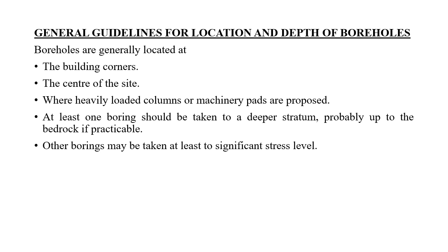Then, as I said, mostly you have to take when you have a plan in your hand. If the plan is already available, then it is always better to do borehole testing. You can dig a borehole beneath all the columns, wherever the columns are coming, as well as wherever heavy machineries or other heavy loads are coming. Okay, then it is always ideal to take the boreholes up to the hard strata or wherever the bedrock exists. Then other borings may be taken to at least the significant stress level.